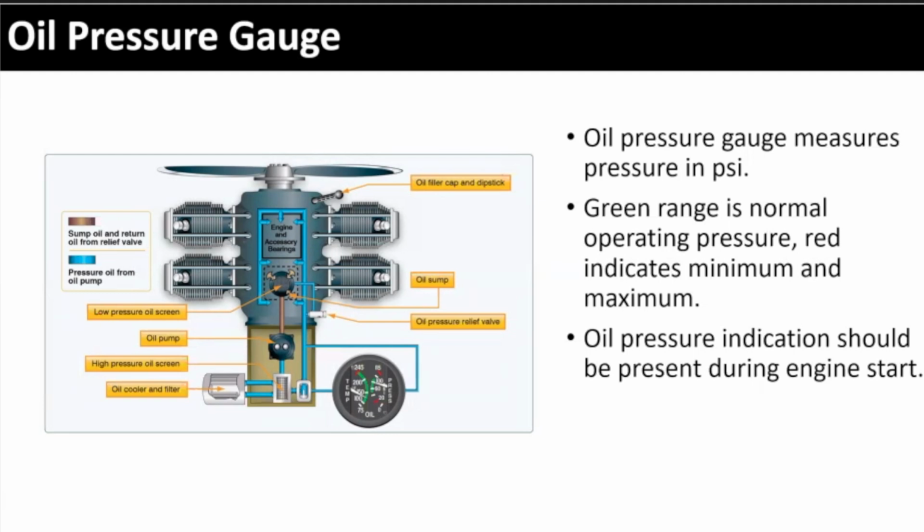What kind of oil pressure do we have when we first start the engine? Low. Zero, basically, right? You're not getting oil pressure until the engine's cranking and circulating that oil. So one of the first things you do, how many lessons do you have? Two? Okay. What's the first thing you do after you start the engine? What's the first check on that checklist after the engine turns over? Check the oil pressure. Yep, exactly.